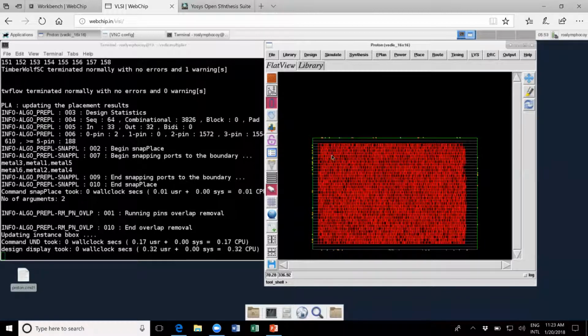So Srinivas has a question: how is CTS done in synthesis without flop placement information? The way it works is basically there is a blif fan-out tool inside Qflow, which is again open source, and that does the clock tree synthesis. Although there are various planned enhancements, like identifying buffers in the standard cell set and specifically marking them as clock buffers. But it's a very different thing.